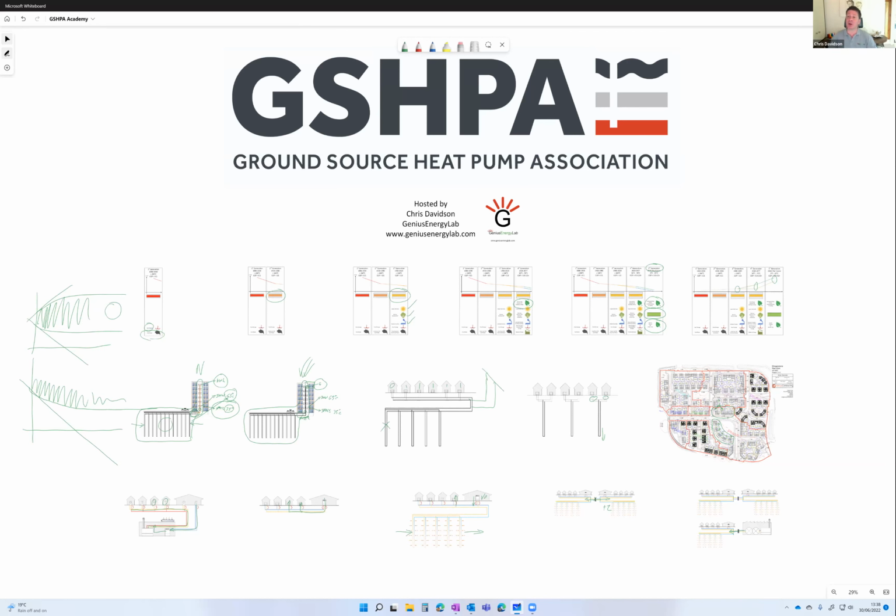Yes, quite a lot of it. Actually, with one of our customers yesterday, I was analysing about 15 networks across 6 or 7 sites, analysing performance data for that and looking at how the performance of the network is diverging from the predicted performance of the network. And the main reason it diverges is because of the occupancy being slightly different, or the usage of that heat network being slightly different as well.